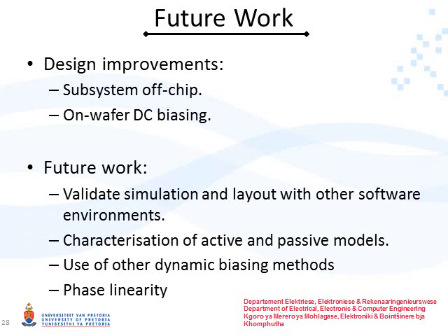The linearity improvement through the use of the APD in this research work focused on the amplitude aspect of the third-order intermodulation distortion component and not on the phase of this distortion component. Future work can be done on investigating and incorporating both amplitude and phase linearity improvement for power amplifiers at 60 GHz and above.